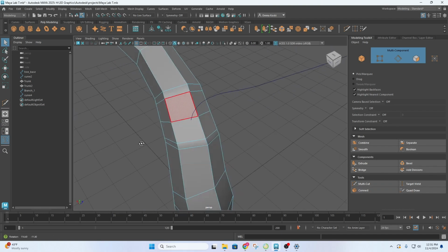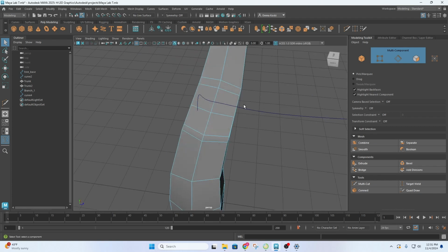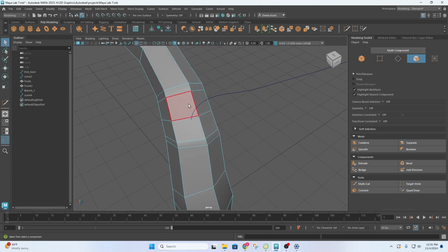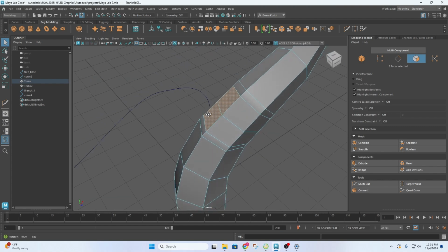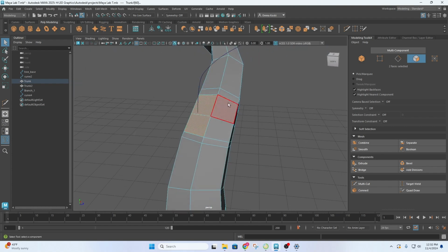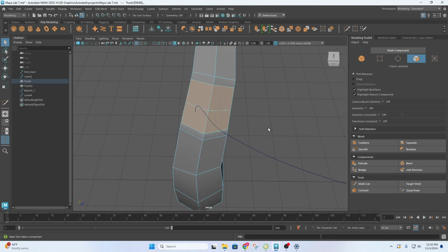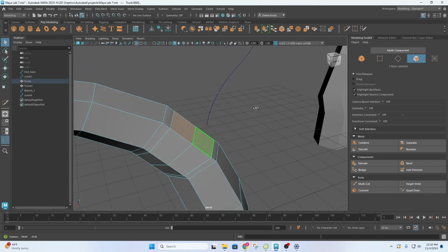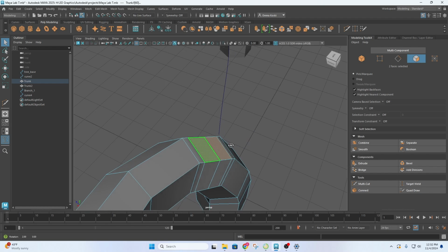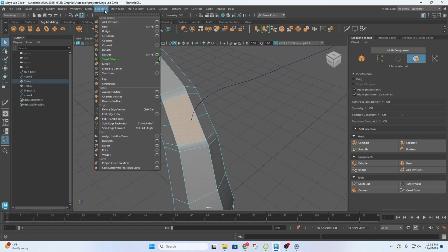But the next thing I want to do is make it so the parts that I want to extrude look more like a circular tree branch, because I don't want to extrude a very boxy shape. I want to extrude a spherical or cylindrical shape. So the way we're going to do that is right-click menu, face selection, and then either click on two of your faces, or if where you put your line split four faces, then you can click on all four. Either way is fine. I'm going to click on two because where my branch is coming from, it lines up better with these two. And then go to Edit Mesh and Circulize.